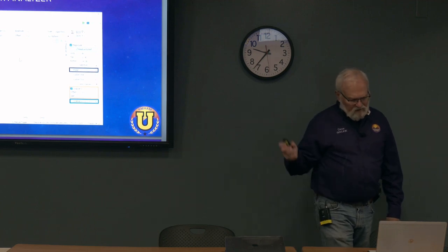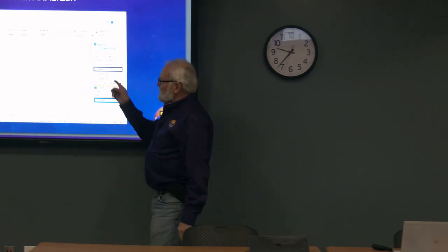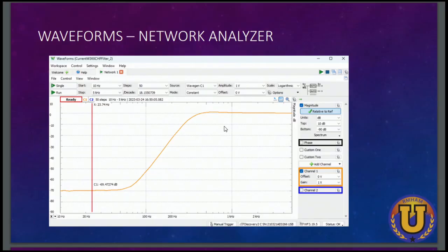This is a network analyzer. This waveform I took off my screen, and that's this filter. It's a really nice CTCSS filter made by Masters Communications. That's Kevin Kuster and the Repeater Builder guys. To test it, I built a little test board that I'm using to test some other things, and I set it up so I can plug the Analog Discovery 2 onto the end of it, like that.